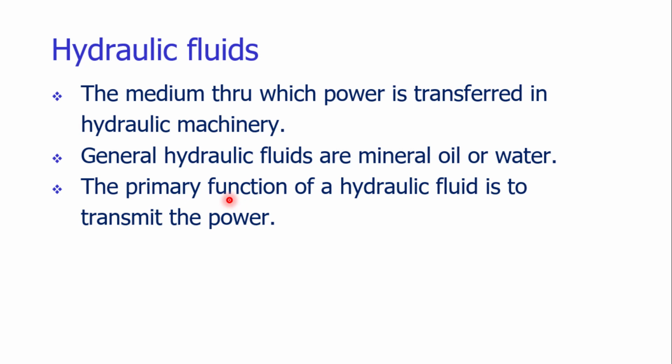The viscosity of the water is also a concern. The viscosity of the water is low, so we need a little high viscous fluid. For that purpose, the mineral oils are the best choice to be used as the hydraulic fluid. The primary function of the hydraulic fluid is to transmit the power. We have to transmit the power from the pump to the designated load or the desired application.